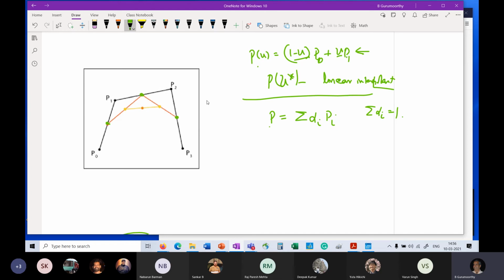Now, the reason why this is significant is that supposing I do a transformation on the point. A transformation can be written as a rotation, which multiplies the point, and a translation, T. So this is some vector x0, y0, z0, and this is the 3x3 matrix. For a rotation about the z-axis, if you go back to either graphics or robotics or any other course that you might have taken in the past, you will see that the term looks like this, cos theta. I think there's a minus somewhere. I'm not sure where.